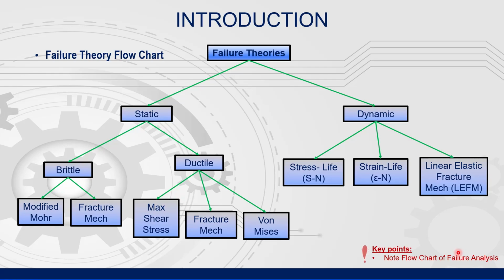When you approach either a design or failure analysis, you start by looking at the loading and determine whether it is static or dynamic. If the loading is dynamic, you have three methods to choose from: stress life, strain life, or linear elastic fracture mechanics. In this course, we will only focus on stress life.